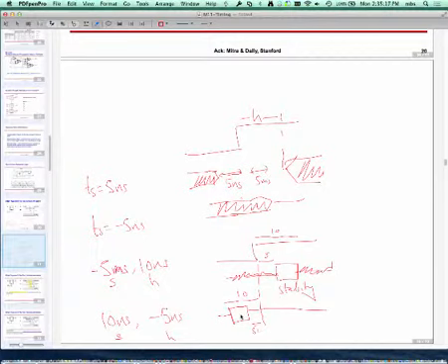So what is happening is inside the circuit it is sampling the data during that window. It is basically monitoring the data at this point. That's the region of stability. Whatever, by definition, because it's stable, that means the data has a particular value there. It's that value that the flip-flop will read.